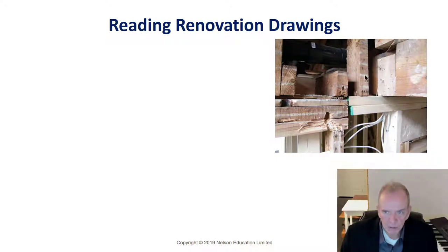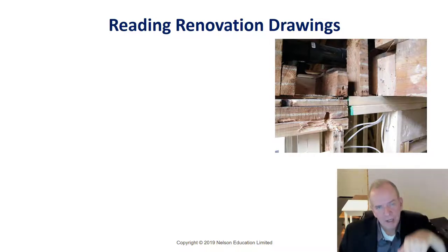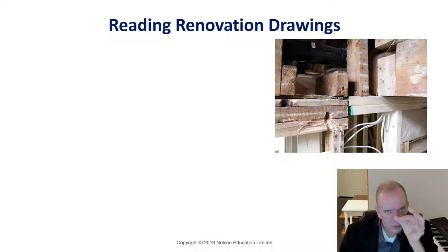And these little lighter strips you see, that was wood lath, wood strips that were put on with a little space between them. And then the plaster was troweled onto it, and a little bit of the plaster would go between that space and hook into the lath. And that's how the plaster stayed on the wall. Of course, we don't do that anymore. Now we use drywall.